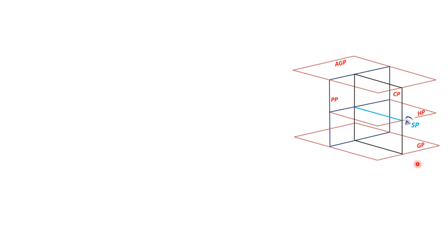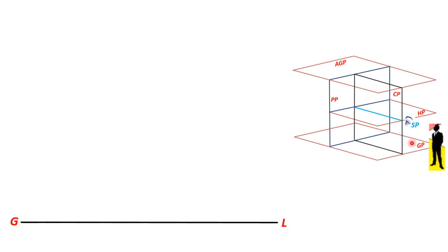In front view, this is the front view direction. You can see the ground plane, the horizon plane, the station point, and also the object which may be placed above the ground plane, on the ground plane or some distance above the ground plane. The ground plane appears as a line in front view, which is the bottommost line in our 2D system.